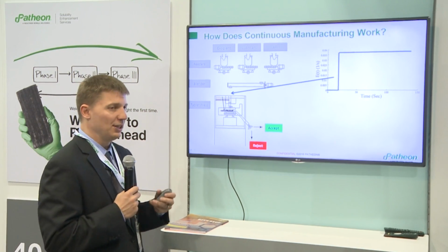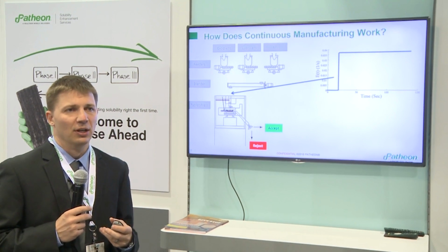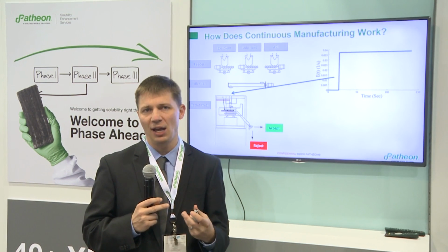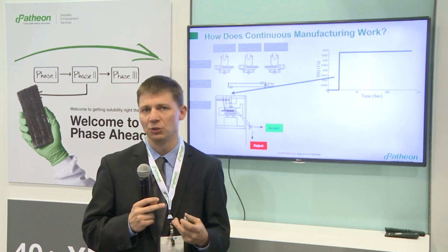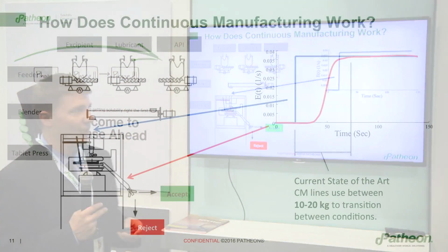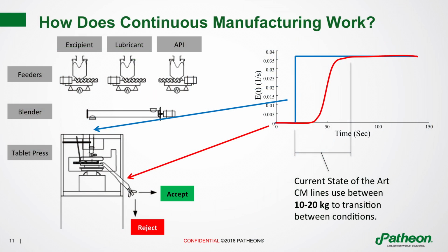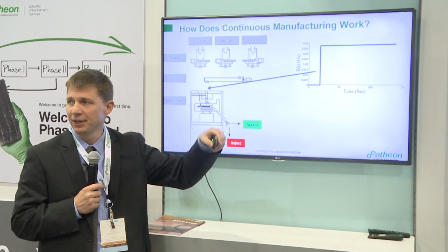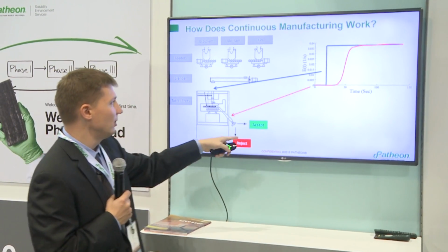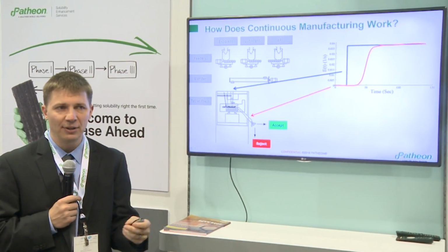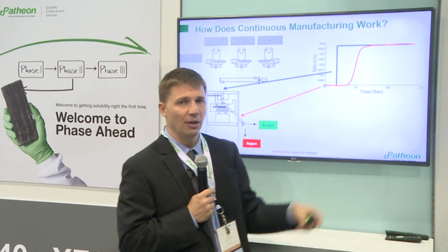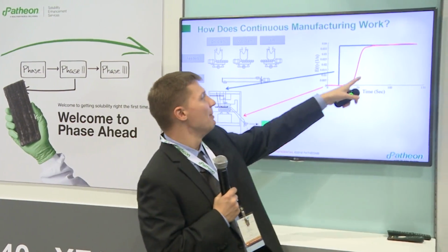So, as I alluded to earlier, this arrangement of equipment means that we can interrogate it with a lot less equipment than what we typically do in the batch world. I'm going to talk about how that works now. If we make a change anywhere within the continuous manufacturing process, let's just say I throw some material in there, that's going to change the concentration, and then I look at the exit, and I wait, and I'm monitoring that exit for that material. After some time, I will see that material come through. And actually on this graph, you can see about a minute later this comes through.